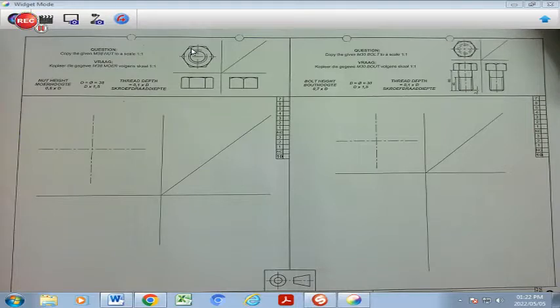That diameter is not given to you, but it has to be worked out. Then you will have 6 tangents drawn flat, top and bottom, and at 60 degrees to the side of the circumference of your circle. Those are called tangents, where the circle makes contact with a straight line.